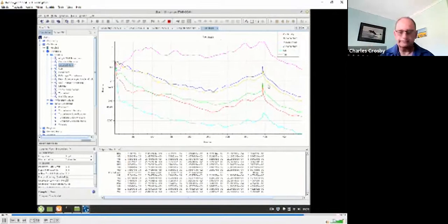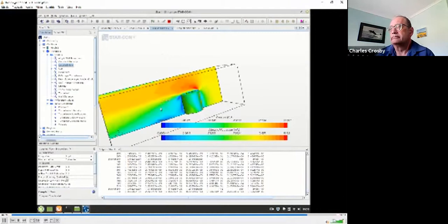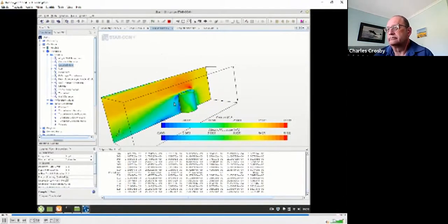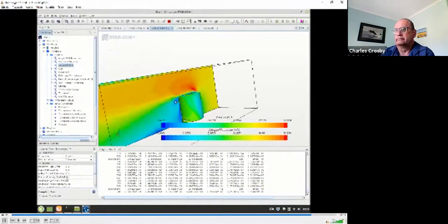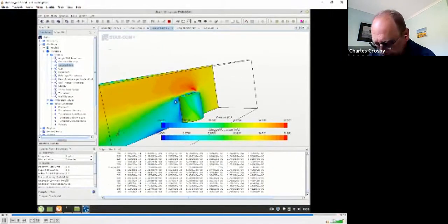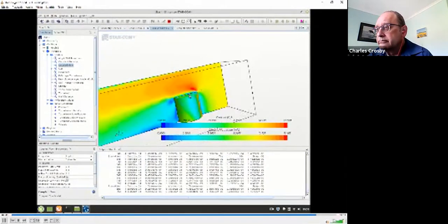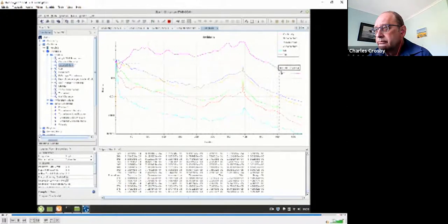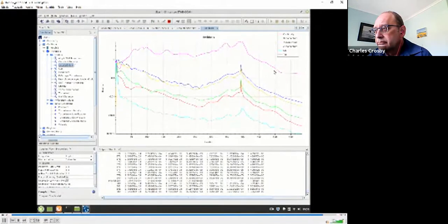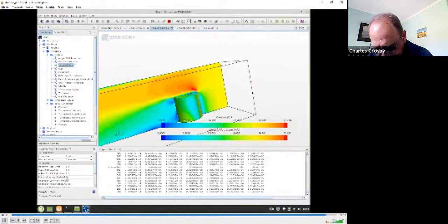Residuals are coming down very nicely. The image, as we saw with Fluent, is a nice smooth simulation which is not actually physically realistic. To capture the more complicated features of this flow, of course you do need to run it with a transient flow simulation, and you should really be running it with detached eddy simulation if you really want to see what's going on, but that'll take much longer. So as before, we're getting fairly nice convergence with first order differencing with a somewhat unphysical solution.